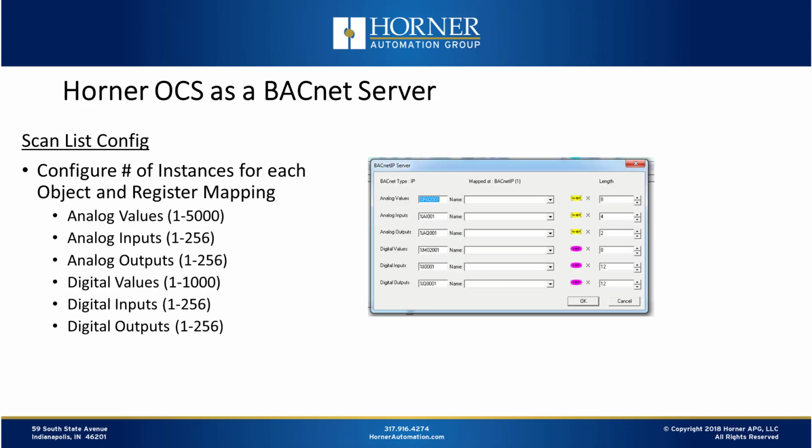And I did mention before that the configuration process for assigning the number of objects and the type of objects that you want to support with your BACnet profile is exactly the same between the two variations of BACnet, and that is true here. So again, you can support the same objects with the same limits in terms of the maximum number of each object.